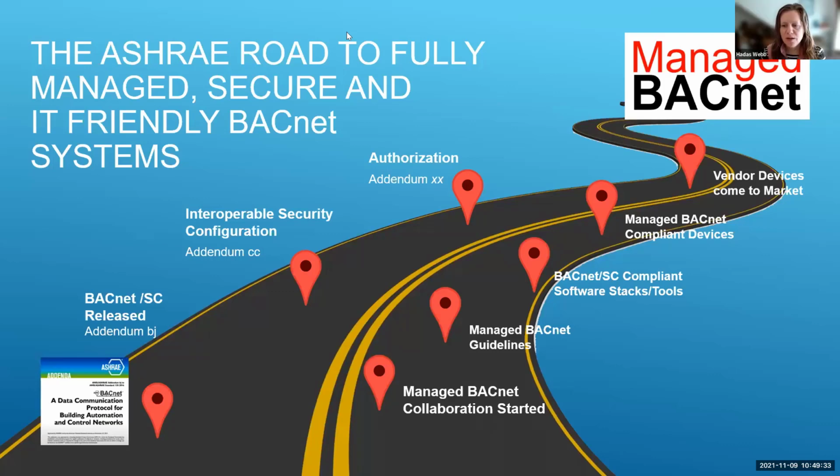One more question came in also from Darius. What happens to BBMD with SC? There are no BBMDs in BACNET Secure Connect. The closest analog to a BBMD in Secure Connect would be the BACNET SC hubs. However, they're different than BBMDs in a number of respects.